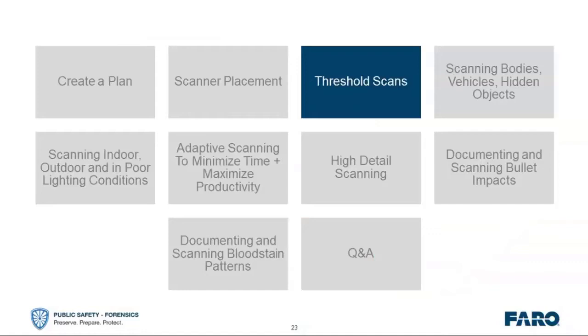We're going to talk about threshold scanning. Threshold scanning is commonly referred to as the connecting scan between rooms or between inside and outside. Remember, you want your project, when you're done, this scanning project should be true and accurate for the scene as it was on that day. It's not necessarily as you found it because you've processed it and you've identified it. If you're scanning in a structure and the doors are closed, but yet you have outside evidence, it's better to leave the door closed so that it is true and accurate for what it was on that day.